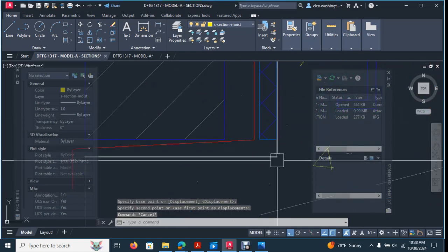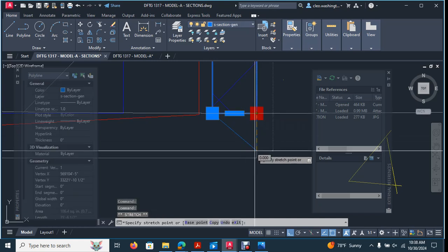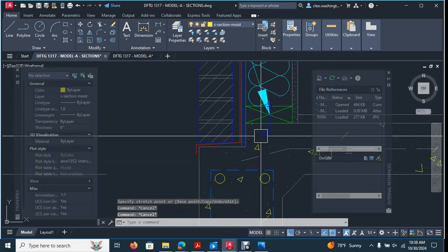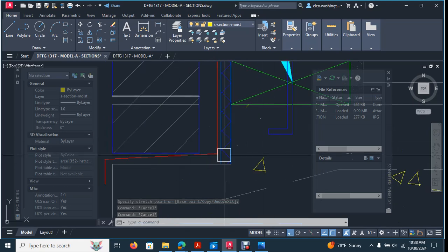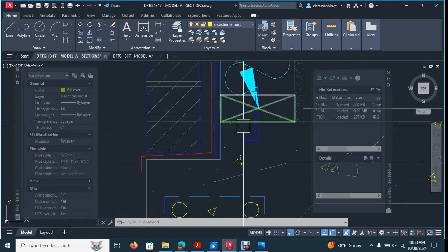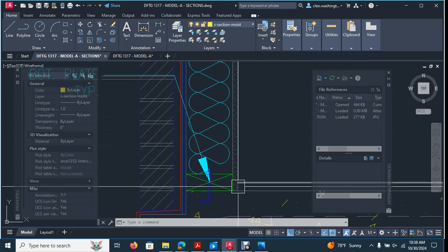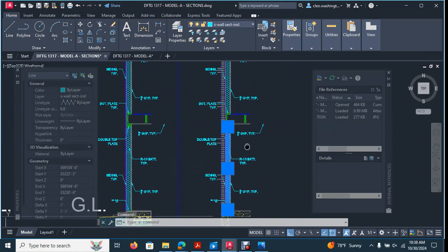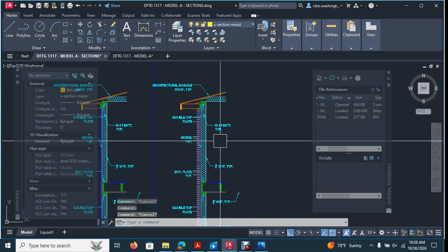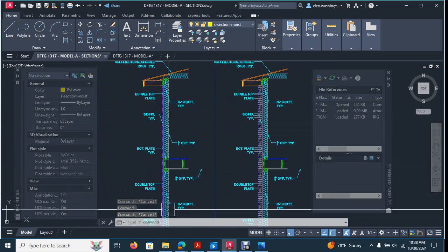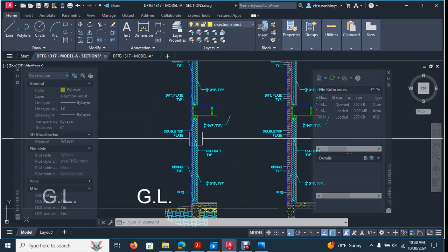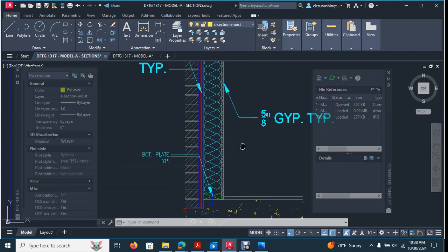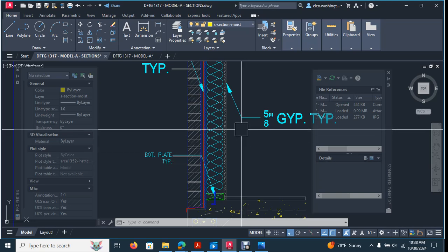Okay, so there you go. And actually, let's go ahead and move the sheathing down just to be consistent. Consistency is the key. So now we have our brick ledge with our brick dap out. We have our waterproofing membrane. We have our 1/2 inch sheathing. We have our actual or nominal size 2 by 4 inch wall stud with the R13 insulation. Okay. So ladies and gentlemen, that's the only difference between the two wall sections where we're showing wall section at the exterior wall that shows the siding, and wall section at the exterior wall that shows the brick.